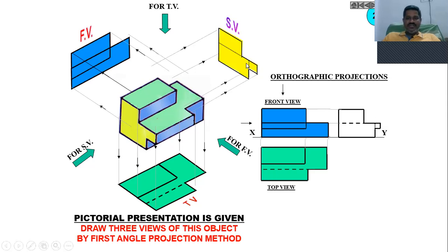Now you take the same replica to the right side with the given dimensions. You take this length, this width and the height, and simply project these lines. Construct the projection, what will be this height and this height, and with the given dimensions construct the side view also.